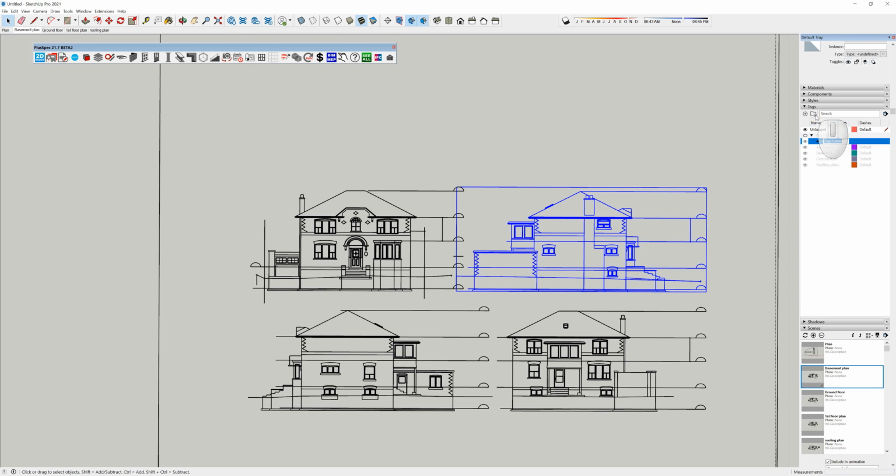and I might also want to create a folder for elevations. You'll notice because it was selected, it created inside of floor plans, and I didn't really want that. So I can actually go and right click and delete. Select on untagged, create another folder, and now I can call it elevations. Enter. Right, so inside of my elevations folder,